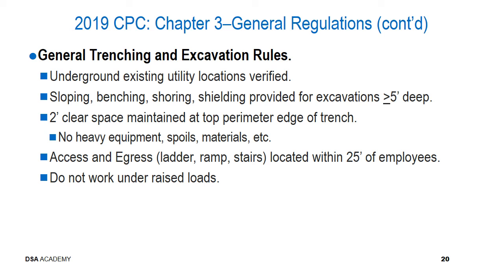An access and egress system, which can either be a ladder, a ramp, stairs, etc., has got to be located within 25 feet of all employees in the trench. Do not work under raised loads.